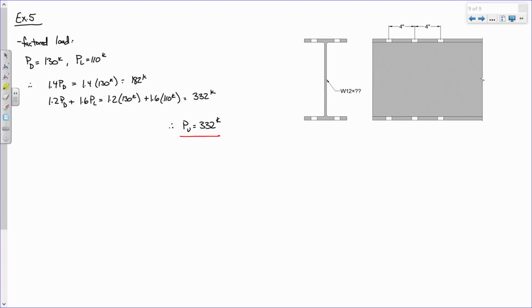And we are actually going to encounter that problem, not just in steel design, but in concrete design. How do you design a beam when you don't know the self-weight of the beam? And so you have to guess a number. And you'll end up coming up with a design. You may have to iterate that design because you guessed that the beam would weigh 50 pounds per foot and it actually weighs 200. So you have to go back and iterate it and check. And so that's just the nature of the beast when it comes to design. But for tension members, we can largely ignore it. That's a great question.